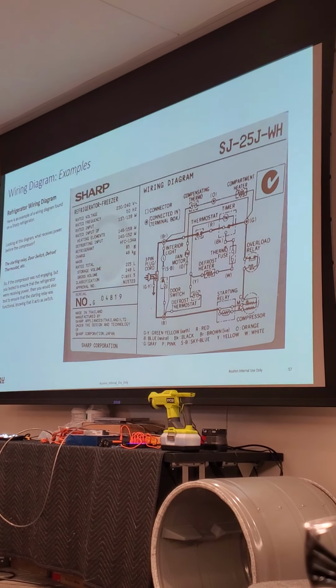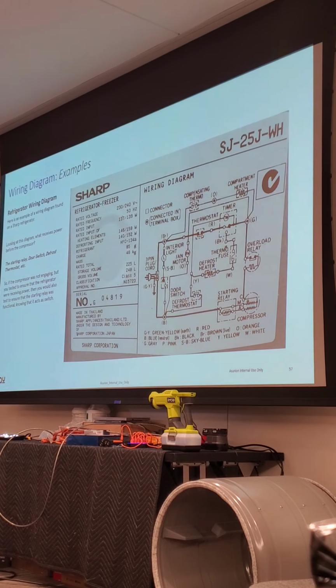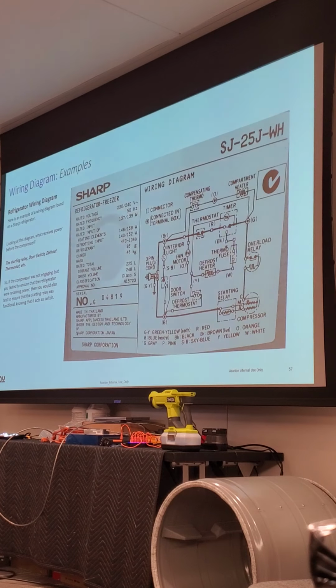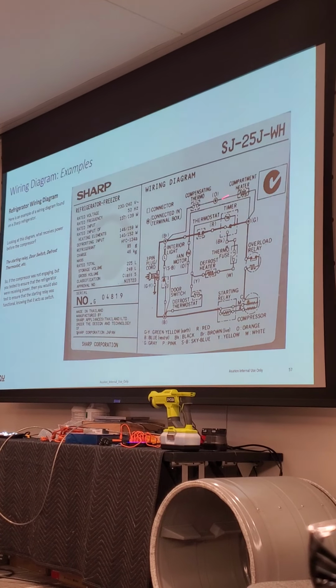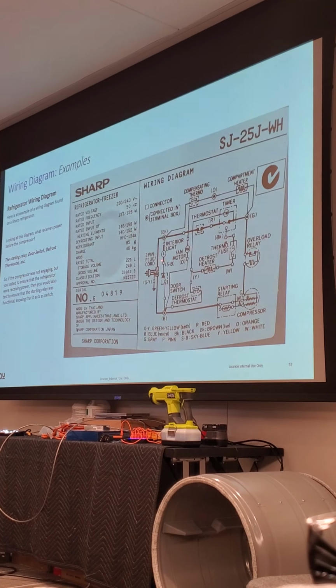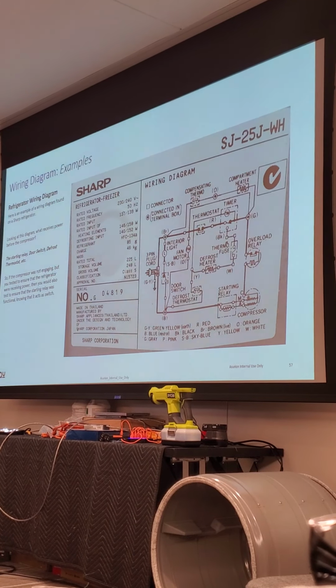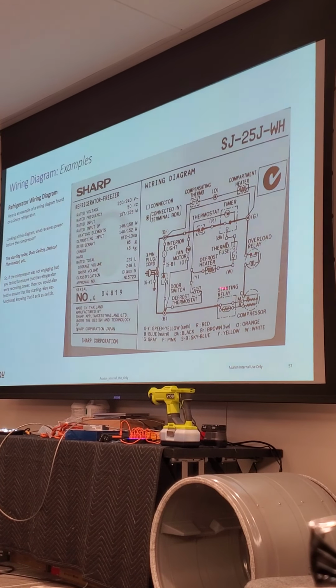So if the compressor was not engaged, but you tested to ensure that the refrigerator was receiving power, then you would test what next? I would check that timer, make sure it's not in a defrost cycle. I would check the door switch. I would check my power source. What else would you check? Thermostat. I would check my overload here.